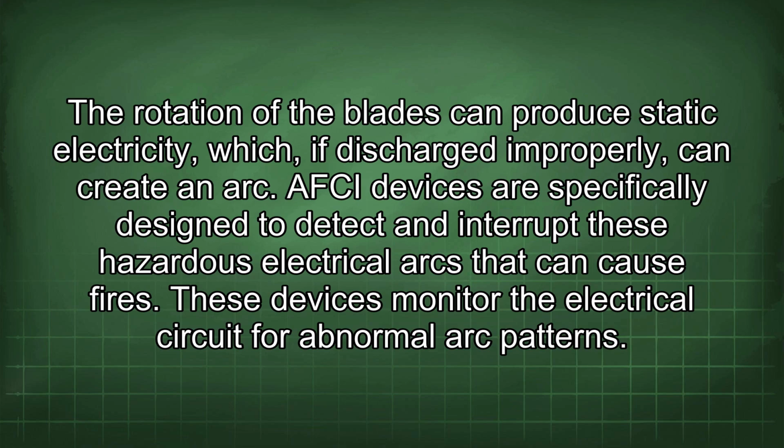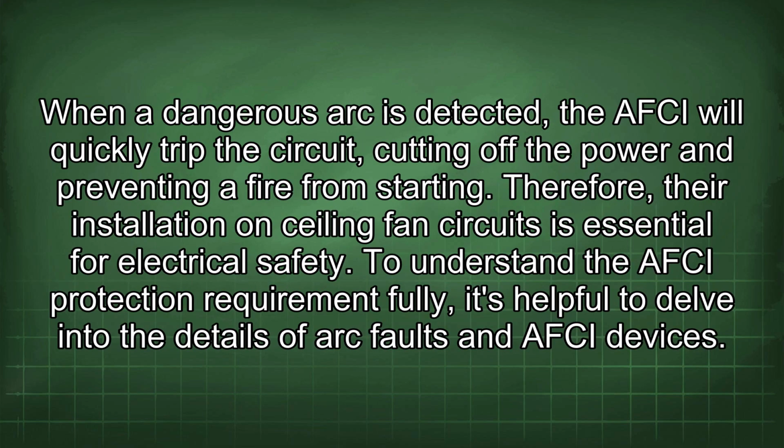AFCI devices are specifically designed to detect and interrupt these hazardous electrical arcs that can cause fires. These devices monitor the electrical circuit for abnormal arc patterns. When a dangerous arc is detected, the AFCI will quickly trip the circuit, cutting off the power and preventing a fire from starting. Therefore, the installation on ceiling fan circuits is essential for electrical safety. To understand the AFCI protection requirement fully, it's helpful to delve into the details of arc faults and AFCI devices.